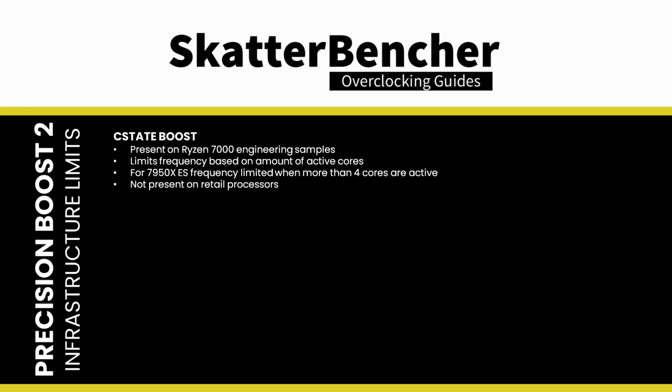C-State Boost is a specific boost limiter present on early Raphael engineering samples. Effectively, C-State Boost limits the maximum frequency when a certain number of active cores is exceeded. For the 16-core 7950X, the C-State Boost limit would force the CPU to run at 5.2 GHz when more than 4 cores are active. This precision boost limiter is not active on retail processors.